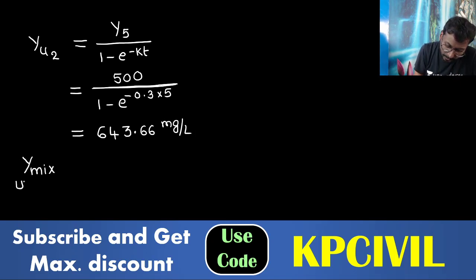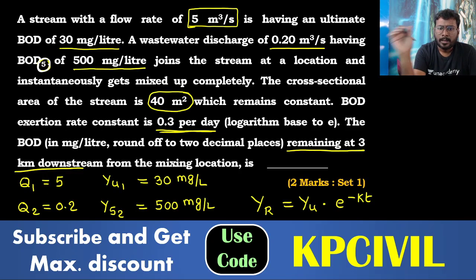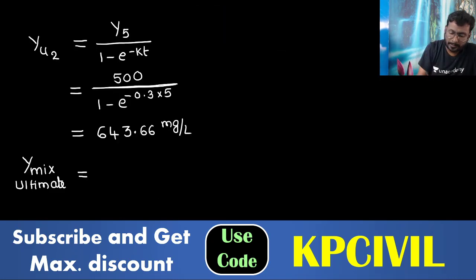Now both are mixed at one point. Mixed ultimate BOD formula, weighted average: Q1 Y1 plus Q2 Y2 by Q1 plus Q2. Q1 is 5, Q2 is 0.2, Y1 30, Y2 643.66.